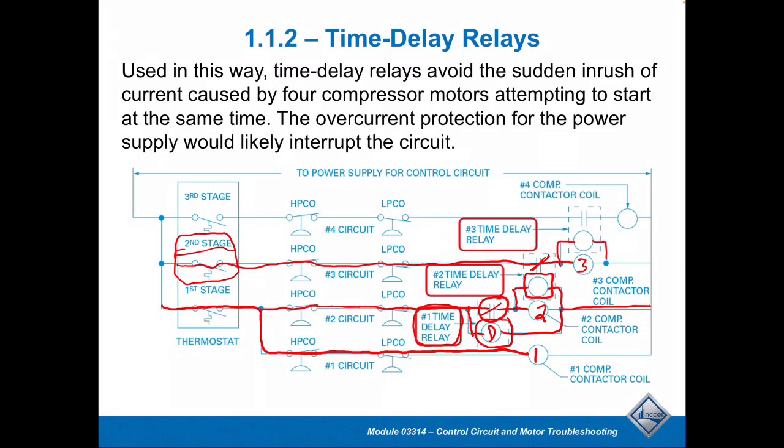And then, of course, if there's a continual energization that's needed or some additional cooling, they'll flow right through here and go through the contacts. After an appropriate delay is set up in here, that would close, and then it would allow this. So you're not going to get all of these compressors to operate and start up at the same exact time, which is what we want, and that's one of the reasons for the delay. And there's a number of different applications that we would do with that.